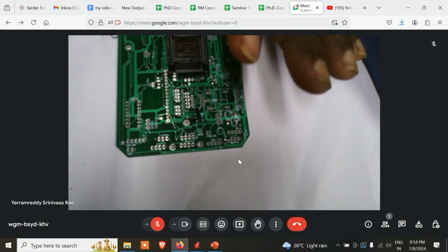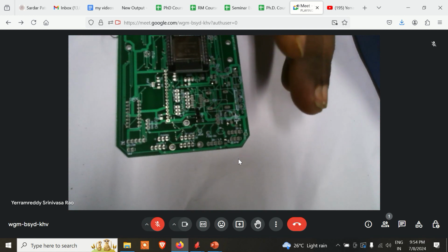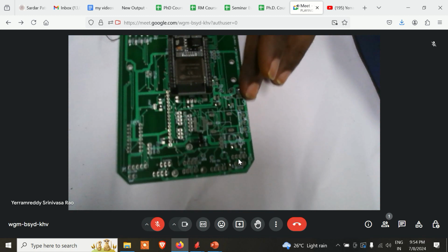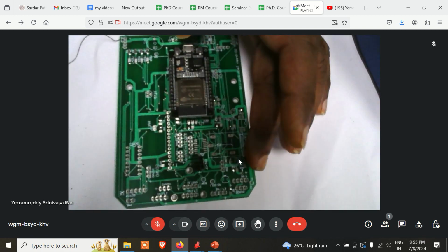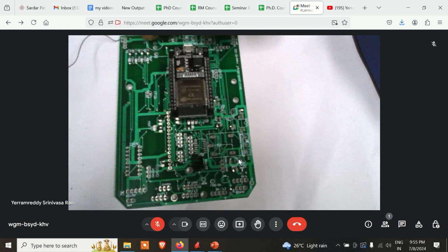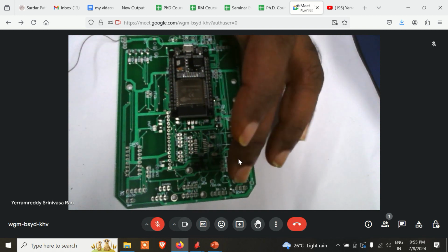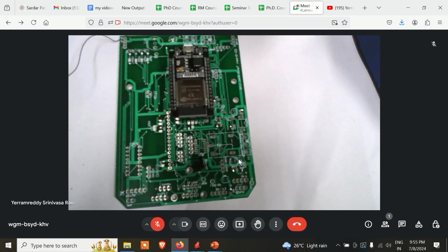So let's stop the soldering part here. Similarly, you can continue with the rest of the components, but the reason for stopping now is we'll write a program first for LEDs, whatever I thought in the previous sessions, and for the sensors, particularly switch or some digital sensors, we'll mount them on the socket where it matches, and we'll verify the programs first, and we'll slowly populate the rest of the components.